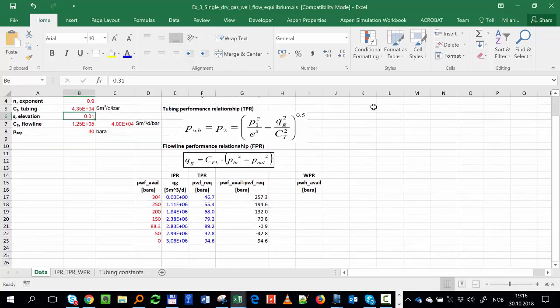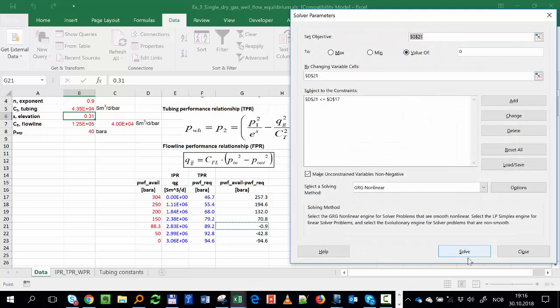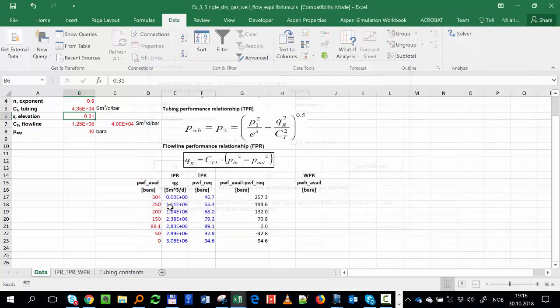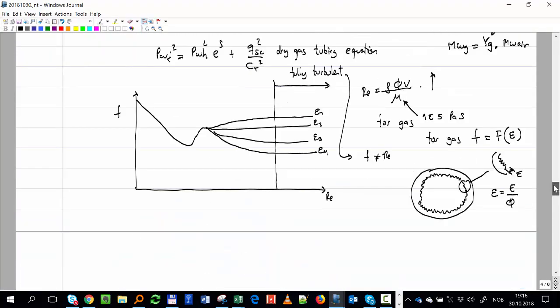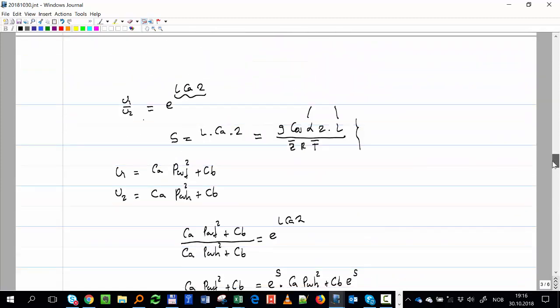And you see, does it change the equilibrium very much? To calculate, if you remember what we have done at the beginning of the class, we are using some average properties, average temperature and average deviation factor. That one is calculated with an average pressure, but we don't know it yet, right? That's something we have to calculate.